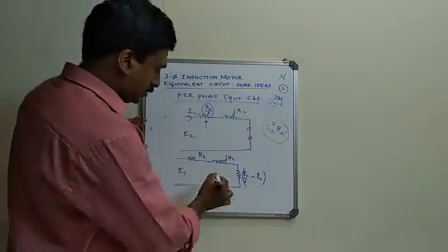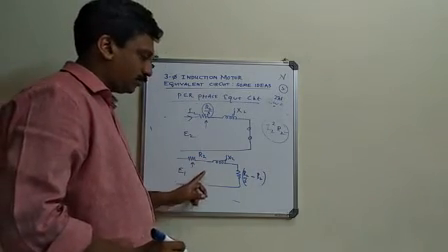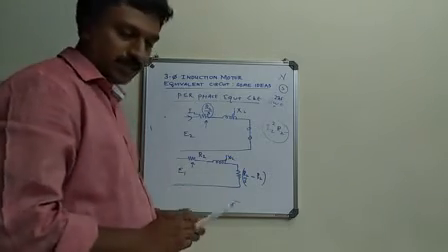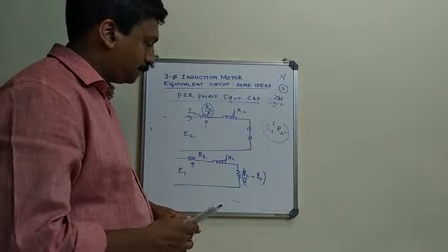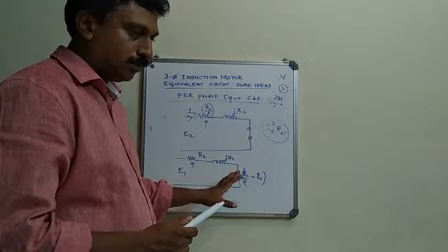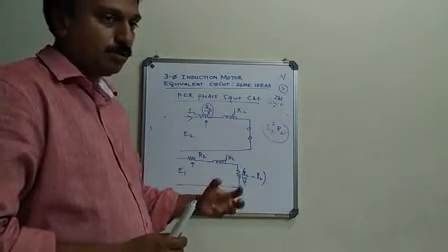In this way you can see that copper loss is there, and the rest of the thing represents something else. That something else is nothing but the electrical equivalent of the mechanical load that is appearing on the shaft.